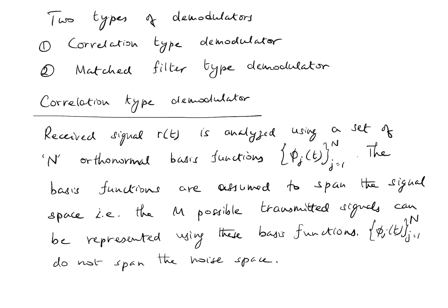The first was to synthesize the signal in terms of the basis functions by using the projections and the basis functions, and the second was to analyze a given signal by using the basis functions. That means we found the projection of the signal onto each of the basis functions, and those projections became our vector representation.